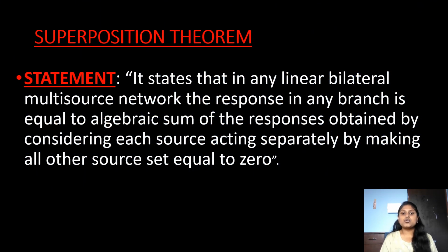The statement of superposition theorem states that in any linear bilateral multi-source network, the response in any branch is equal to the algebraic sum of the responses obtained by considering each source acting separately, by making all other sources equal to 0.